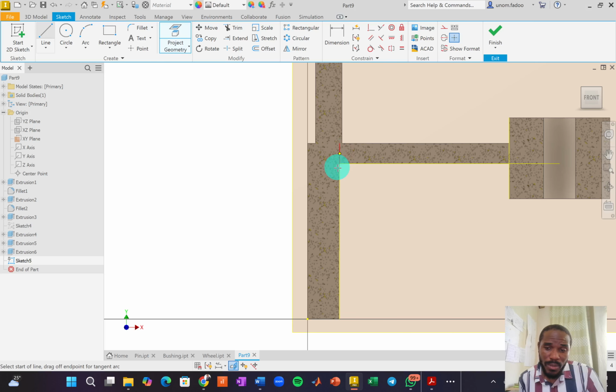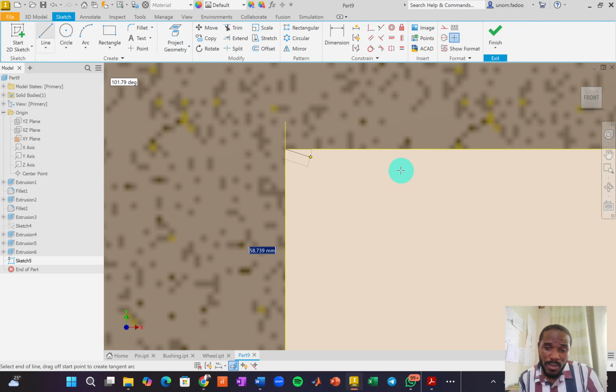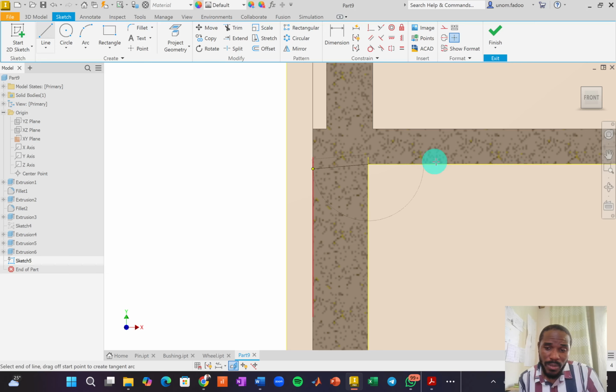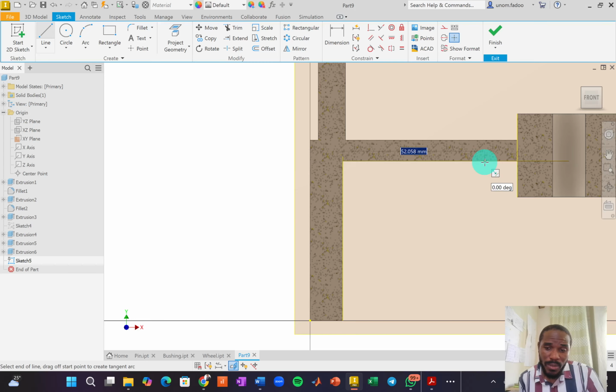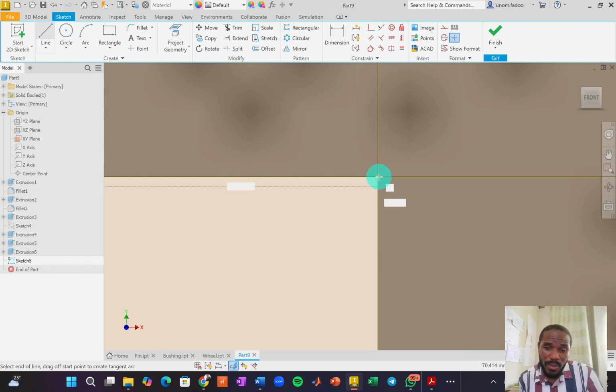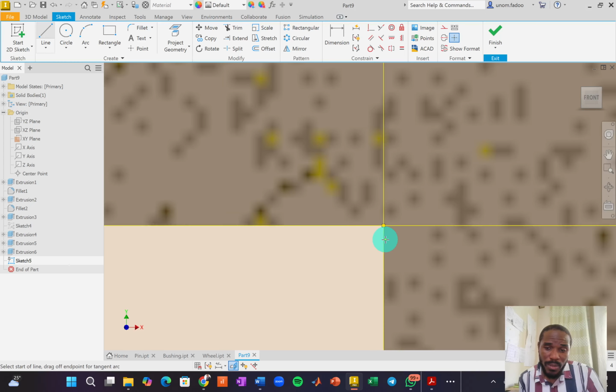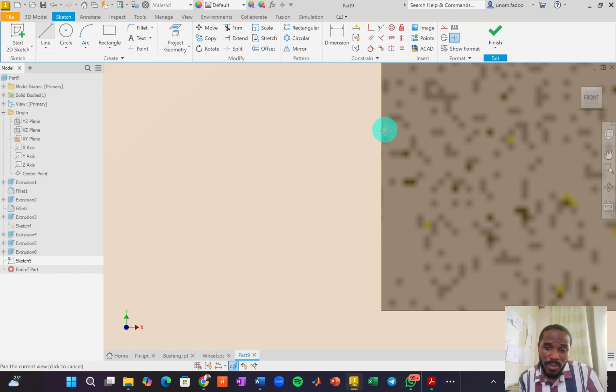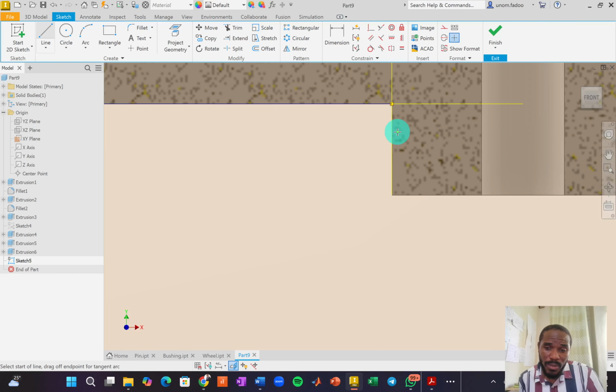So I'm going to pick my line tool. I'm going to draw a line from here. The reason why I projected was so that I can easily do snap to grid, okay, and get the exact. So let's zoom in and I want that to stop here, okay, and now that is a circle, right? If I do it bang on, if I Control Z, if I do it exactly at that point, what will happen will be that your circle will curve, and then you will just have the wedge just touching the circle at one point as though it were a tangent.